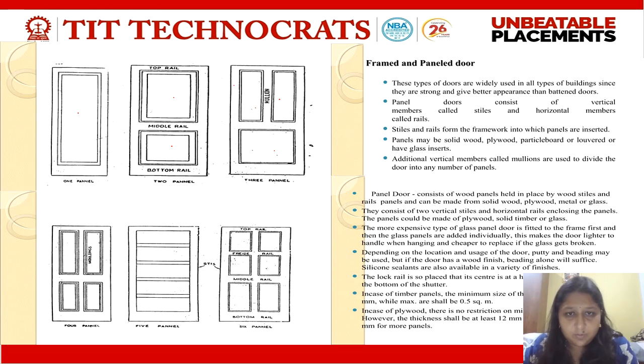This again is a vertical post. This portion, this vertical area, it is called as stile. These are the horizontal ones, the area created is called the rails. In between this, the vertical gap created or the portion created is called as what? Panel. This is one panel. This is the other panel. Okay, this is the first panel. This is second. This is my third panel. Okay, so the member between the two panels in the same rail is called a mullion or muntin. These are the muntins.